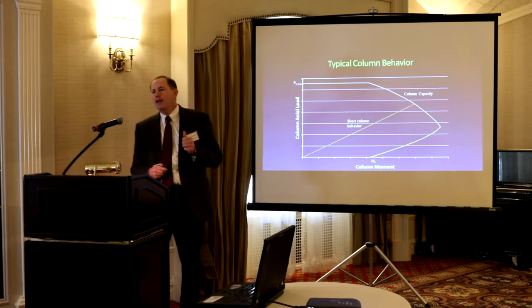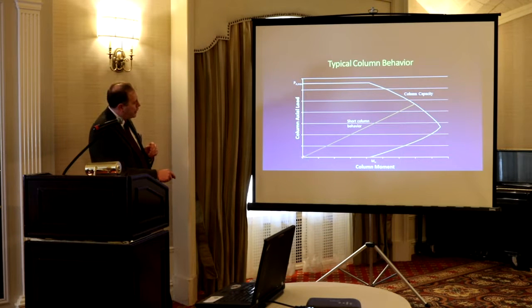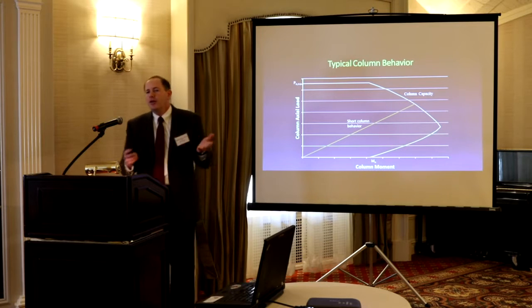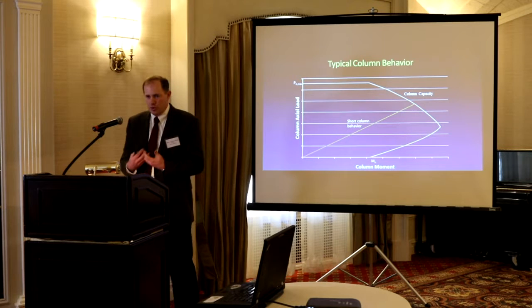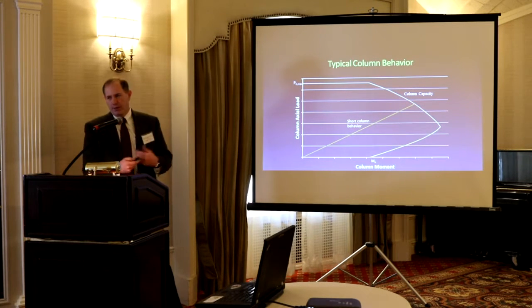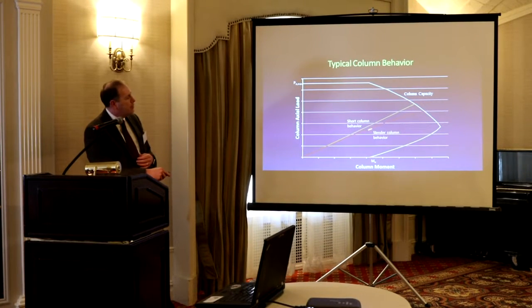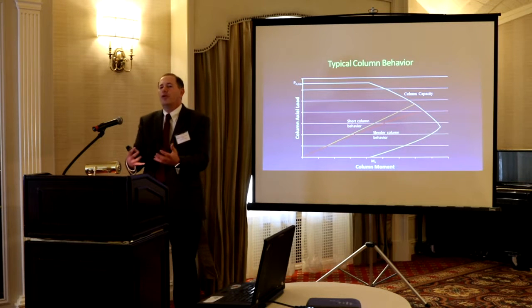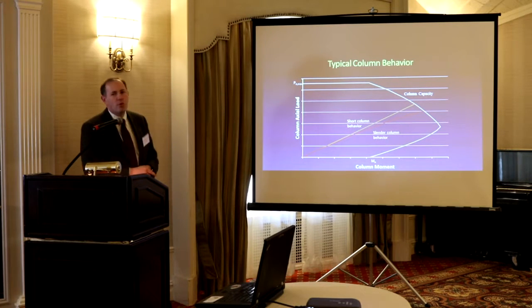If I have a short column, and I would load it up, and so I start here, zero load, and I start loading, and as I load, if I have some moment on there, it's going to linearly increase, and I get this straight line until I hit capacity. And that's what we teach in an introductory structural concrete class to students. I want to stay inside of this range because outside it will fail, inside I'm good. As I continue to increase, because of the bending, there are second order effects, and it produces more moment than what I have for the same load. So if I'm at this load level, I actually have an increased amount of moment I need to resist.